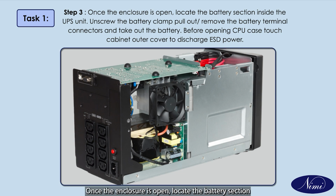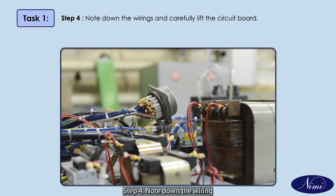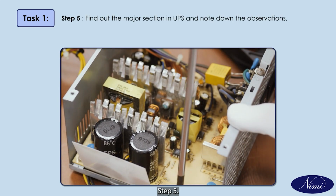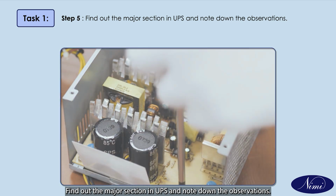Step 3. Once the enclosure is open, locate the battery section inside the UPS unit. Unscrew the battery clamp, pull out or remove the battery terminal connectors and take out the battery. Before opening the CPU case, touch the cabinet outer cover to discharge ESD power. Step 4. Note down the wirings and carefully lift the circuit board. Step 5. Find out the major sections in the UPS and note down the observations.